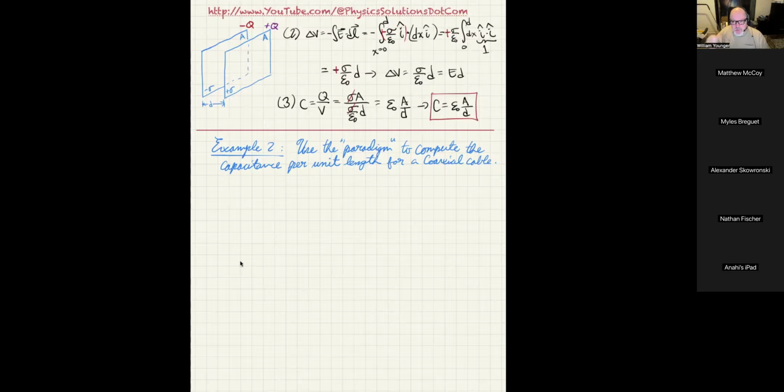If you cut back the housing, you'd see it was actually braided, something that looks like a stainless steel or aluminum screen, but in a cylindrical shape like this. And then inside of that is some white dielectric material. And then at the center of that is a copper wire. That copper wire is one of the terminals, and the aluminum screen around the outside is the other terminal.